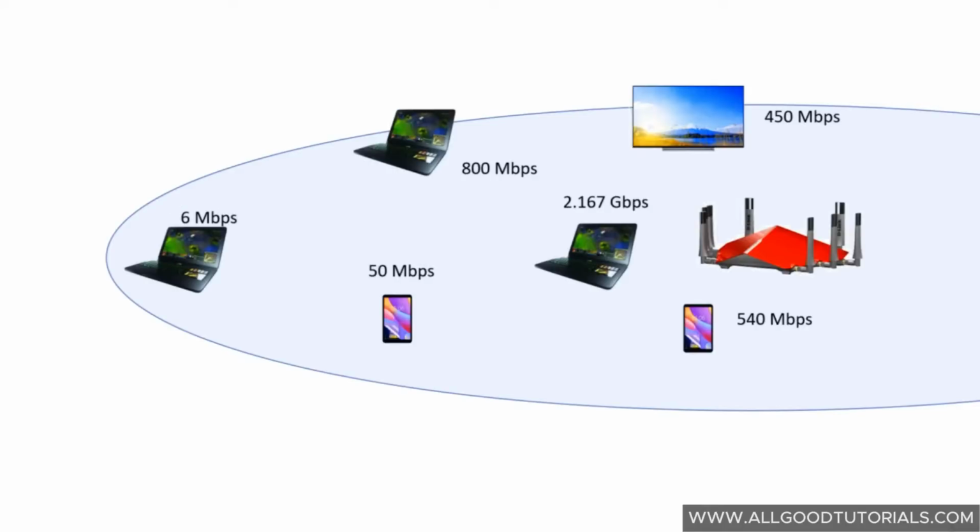So depending on where your equipment is in the cell, it's going to experience different data rates. If your equipment is distributed through your home, your average data rate is going to be somewhere in the middle. In this particular illustration, where I have 6 devices operating at different data rates, my average data rate is actually about 670 megabits per second, which is quite a bit below the advertised 2.1 gigabits per second, but is nevertheless still an extremely good data rate.